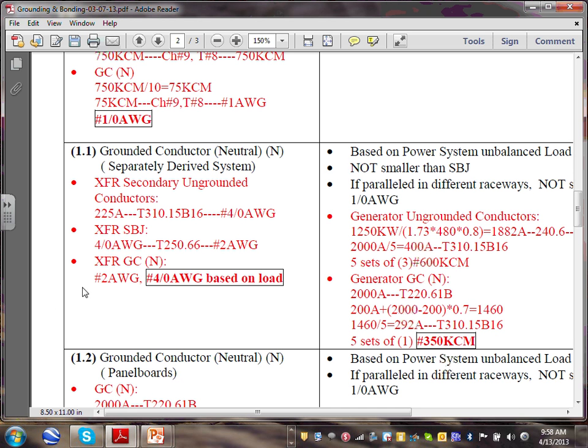So anyway, what's your minimum? Number 2. What I highlighted here is a recommendation: full neutral at this lower level, just because everything, the load, guys, there is neutral load. And there's also harmonics now, because of equipment and so forth. From a safety point of view, full neutral would be the best. At this level, we're at a 225 amp panel level. Could I use number 2? Absolutely.